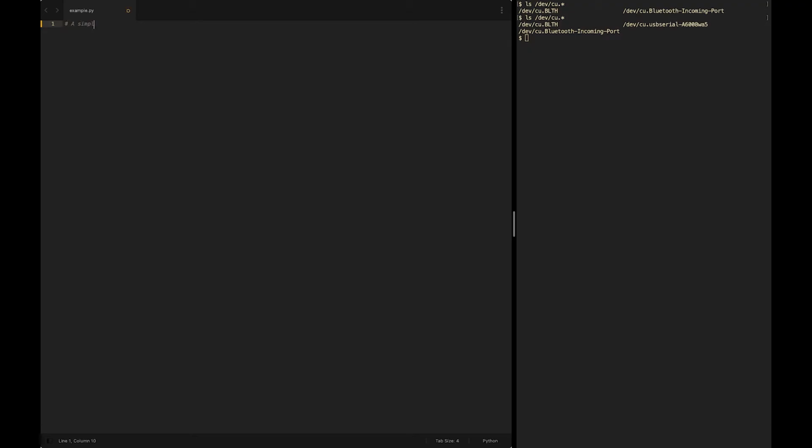Now we can start writing our simple program to initialize the board, set the channels to output and turn a few of them on and off. First we have to import the modules we'll need. Serial to talk to the serial bus, and time to add sleep delays to let the board settle between commands. Next we assign a variable for the address of our board, like so.